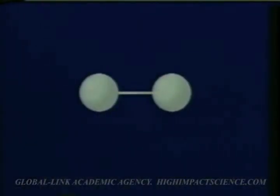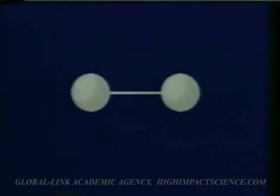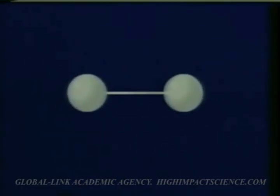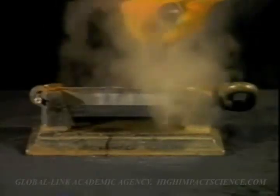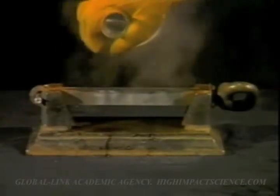As the cooling and contraction continues, slight bending in the iron rod becomes evident. In fact, the iron rod is no match for the forces of thermal contraction and finally gives way altogether. As a material is heated, the frequency and amplitude of molecular vibration increases. The result is thermal expansion. When cooled, the molecular vibrations decrease and the material contracts.